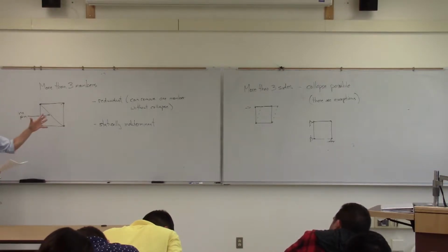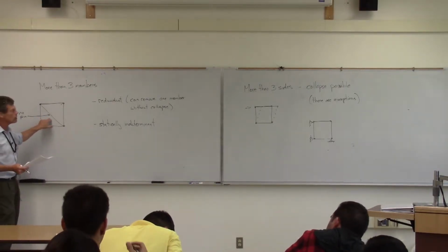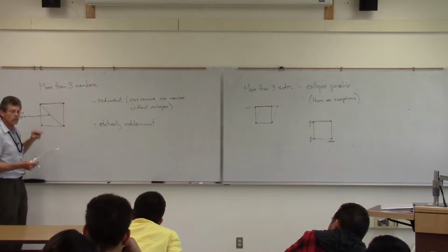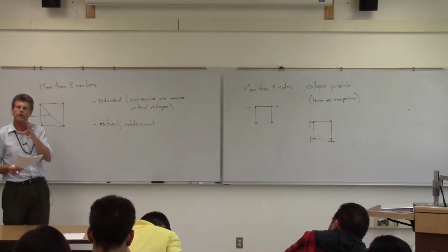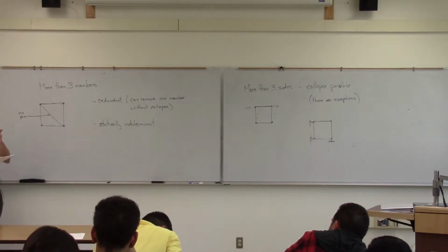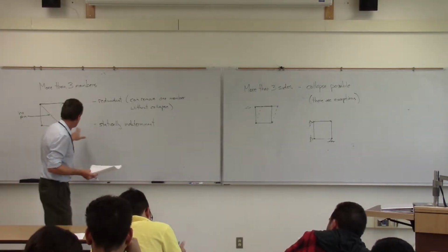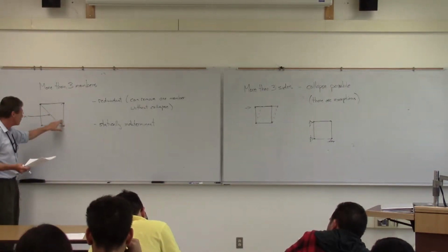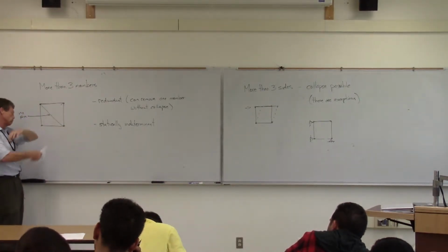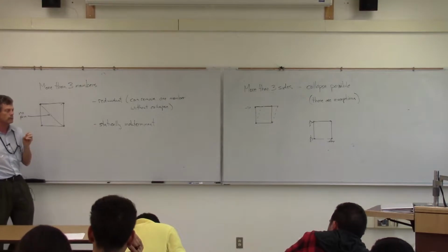Now, we like structures like this. An example of a structure that wasn't redundant was the I-35 bridge in Minneapolis, Minnesota that went down. When you hear bridges described as fracture critical, basically that means it's a situation like this. If one of these members fractures, the whole thing goes. And that's what happened in Minnesota there.